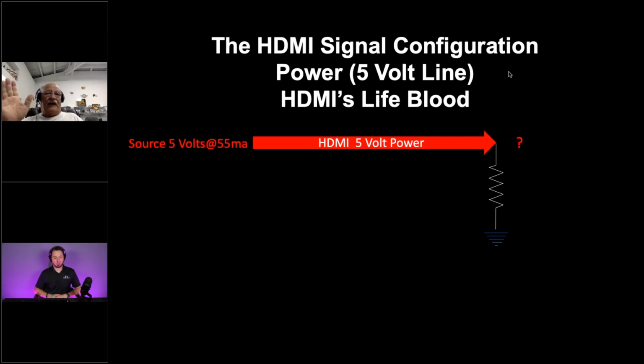So like one of the worst ones out there, Apple TV. Really? Apple TV. I mean, when you load them, they can supply as much as maybe 70 or 80. And you say, well, that's good, right? That's better than 55. Yeah, but you put an AOC on that thing. A typical AOC is going to pull 100. So that's why we see all these problems with AOCs working with Apple TVs, because they're killing the power supply. It's out of spec. These AOCs are out of spec.